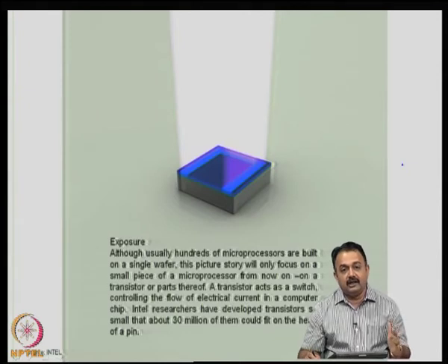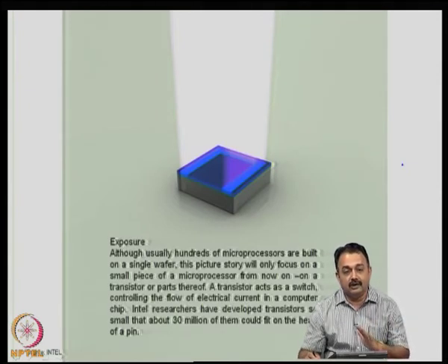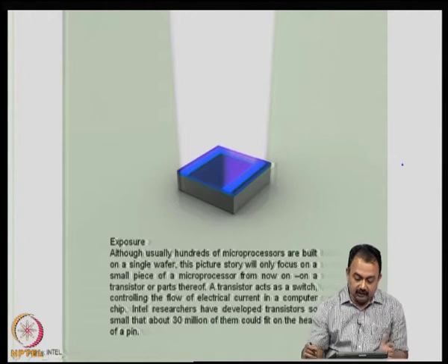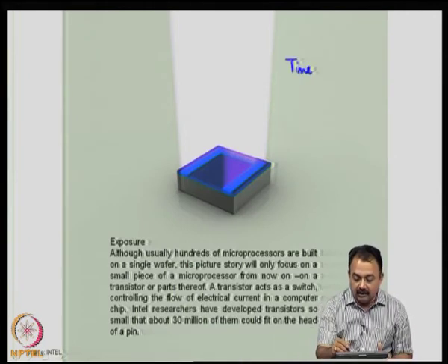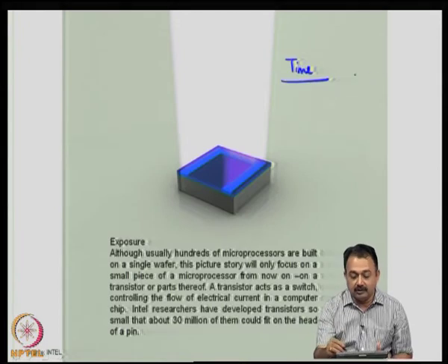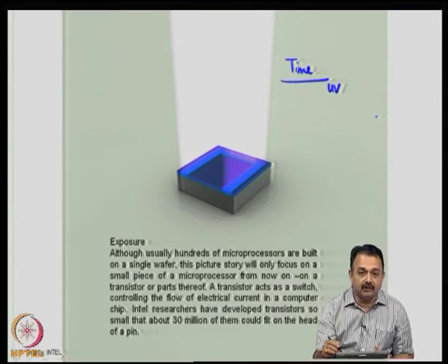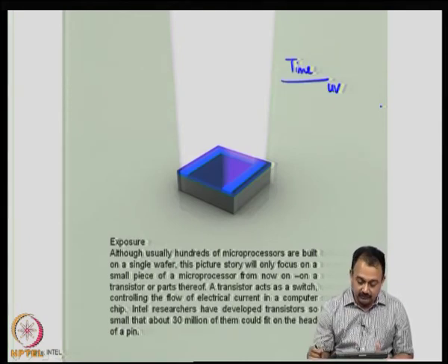So, along this entire exposure process, you do not want any change, any dimensional problem. You do not want to lose any features, okay. And two things, one is the thickness of the photoresist and the time for exposure, okay. Time is also very important. You can't keep exposing the photoresist material to UV light for an indefinite period of time. So, this is also recommended by the manufacturer. All these properties are interrelated, and to get a good image with a high resolution, you need to work on all these issues.